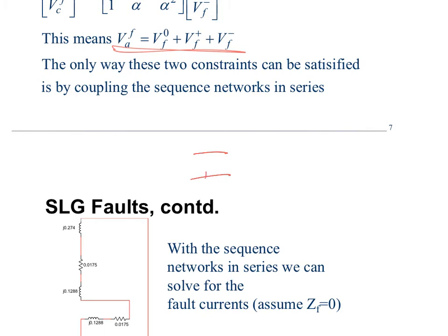So I'm going to take my positive sequence diagram, and I'll model this as a source and an impedance. This is V Thevenin. What is this impedance here? It's Z Thevenin in the positive sequence diagram. This current flow is positive sequence current. This voltage is positive sequence voltage.